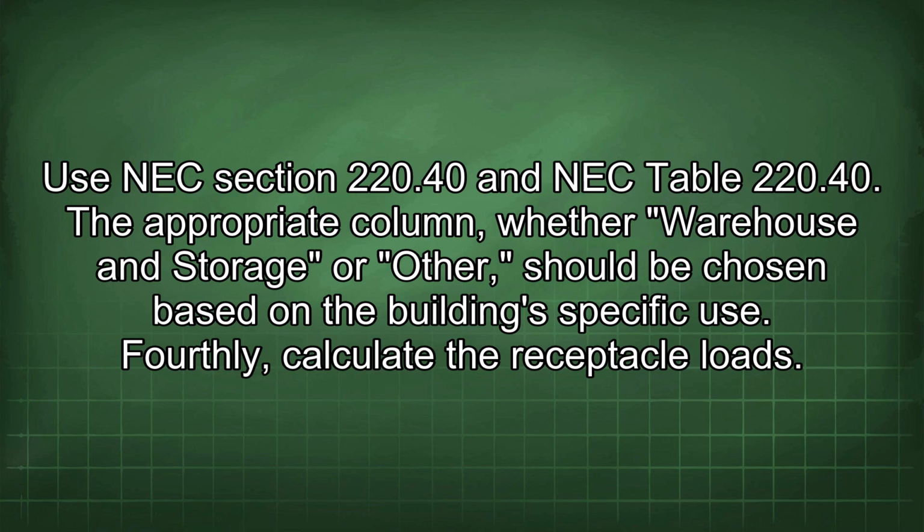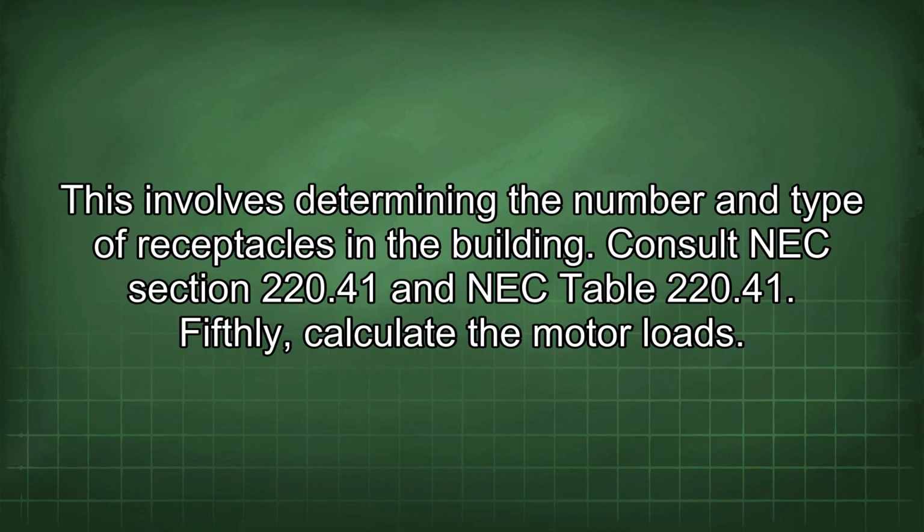Fourthly, calculate the receptacle loads. This involves determining the number and type of receptacles in the building. Consult NEC Section 220.41 and NEC Table 220.41.